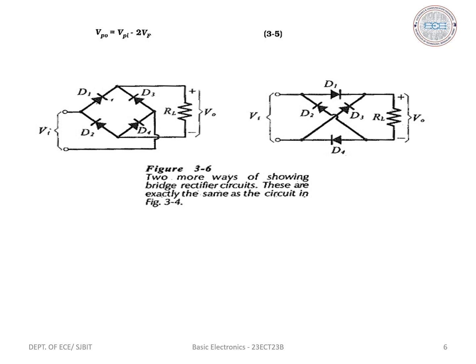During both half cycles of the AC supply, the load current flows through the load resistance RL, hence IL is unidirectional. The load current that is generated is unidirectional. Suppose I connect a capacitor in parallel to the load resistance. C1 is added to ensure that the output voltage remains the same or near the peak voltage even when the diodes are non-conducting. It charges to approximately 16.3 volts at the peak of the positive half cycle and holds the voltage at this level.